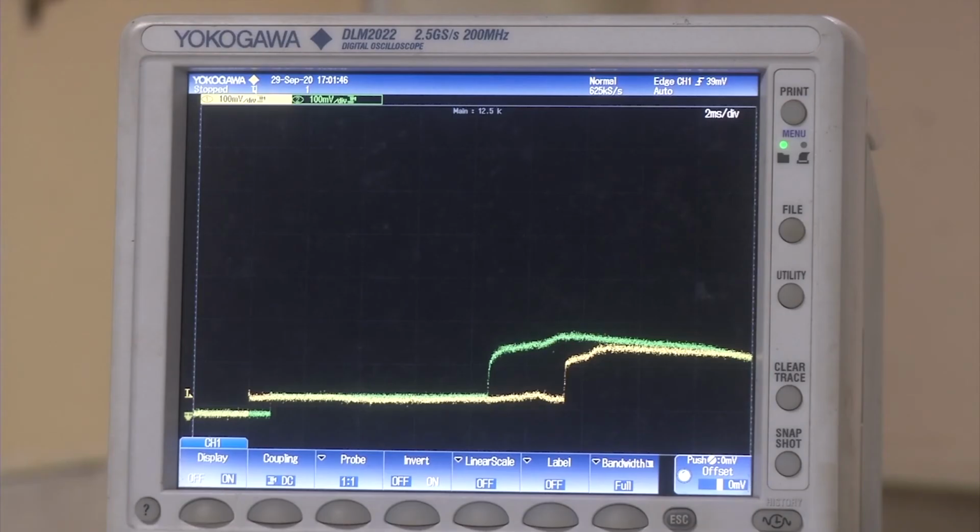So, as you see from the scope, instantaneously the reference line shifts up. You see there are two signals captured in this oscilloscope. The yellow one refers to the first pressure transducer, which is located at 1885 millimeter from this end flange, and